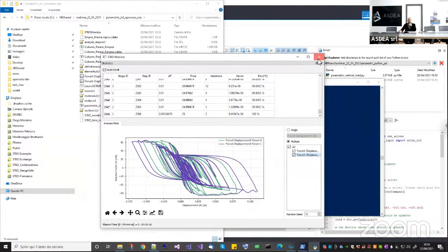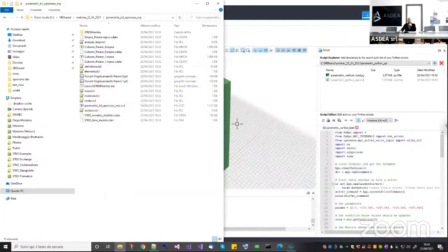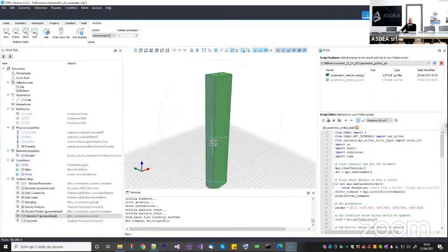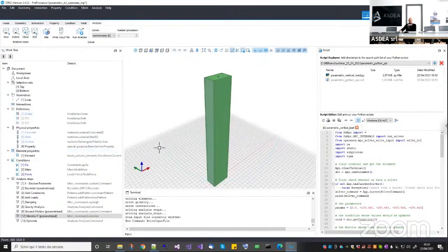Unfortunately, this approach is very easy and useful when you have to parameterize simple things like the ID of the ground motions, which is pretty useful for dynamic analysis when you have to run the same model for multiple ground motions. But if you want to parameterize other things like the geometry or the material properties, and you have your model done in STKO, it is not very convenient to do it with OpenSeesMP.